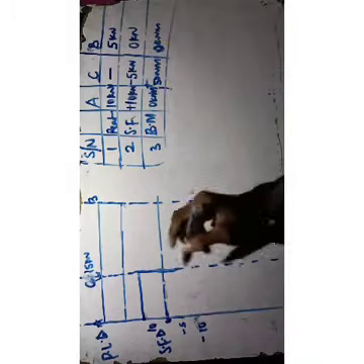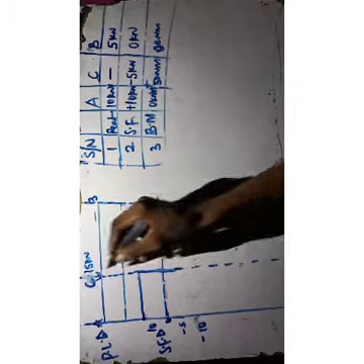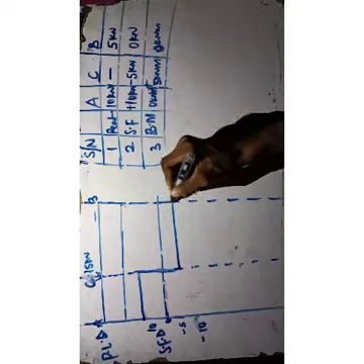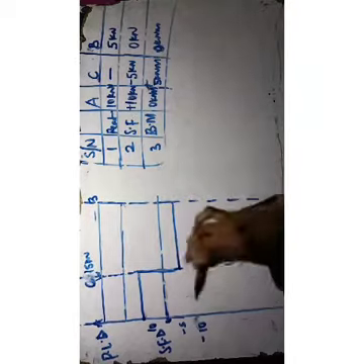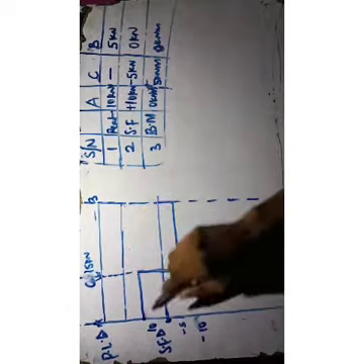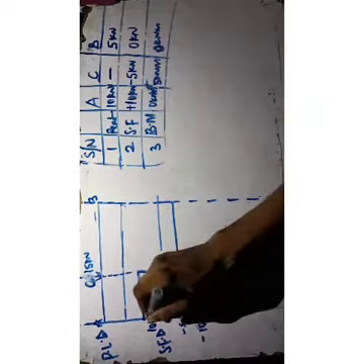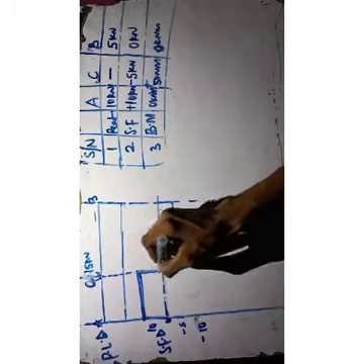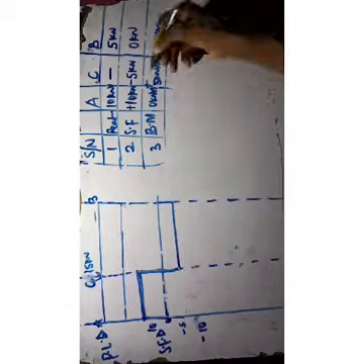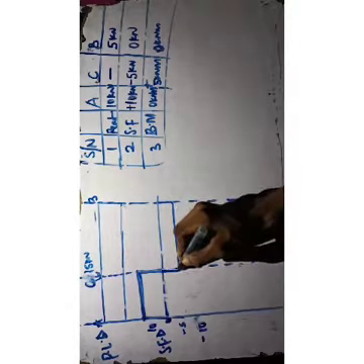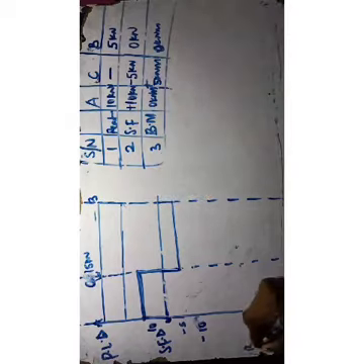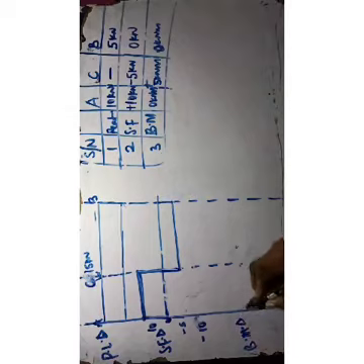And the next thing is 0. So it is constant here. Constant. That is on a straight line. Then it gets back to what? 0. So I have it as 0. So you can say I come again. From here you can find out that the shear force is plus 10. Next thing, minus 5. It's constant rather. From 10 constant and minus 5, you come to minus 5 here, adding it to minus 10. Okay. Then from here it's constant as well, and you find 0, 0.